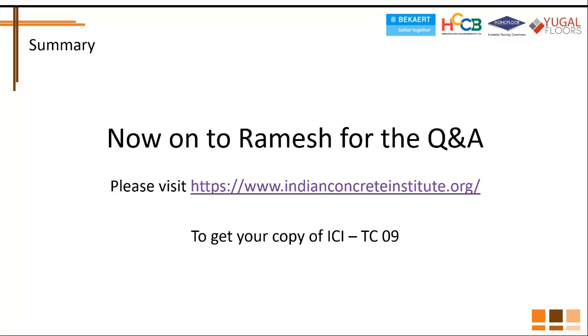Okay. Another question that is coming to you, Navneet, is can we replace steel reinforcement with steel fibers completely in the tension zone? Again, it depends on the type of application. I would not suggest this for suspended slabs because you don't have sufficient load redundancy in the system. We structural engineers use a term called degree of static indeterminacy, which essentially tells whether my element has sufficient possibility of redistribution of stresses. That is not the case there, but for grade slabs, certainly yes, because you have a soil supported system, which is highly indeterminate, and there you have the possibility of load redistribution also. So there, definitely, in the tension zone, 100% replacement of steel is possible.